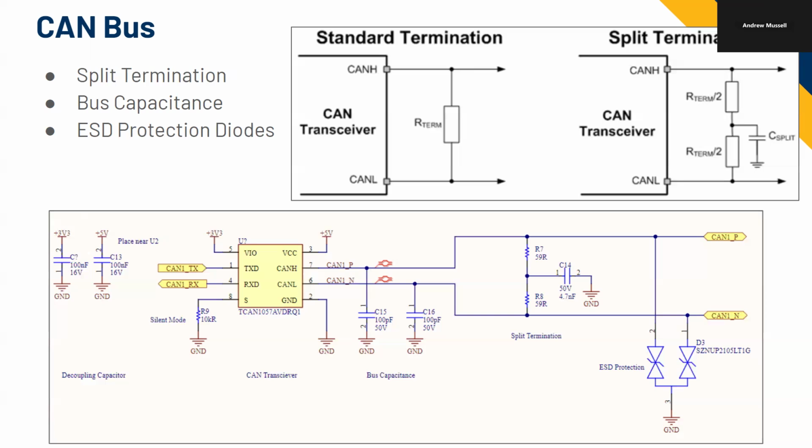We have to have physical fuses as per the rules, but on our low voltage boards, the TPS2482 that we talked about earlier, which uses I2C and does all the power telemetry, is actually an e-fuse chip, which is an electronic fuse. If it senses too much current going through, it has a MOSFET and it'll disconnect power. That reacts much faster than a real physical fuse. Also, real physical fuses burn, so when one burns, you have to go in, desolder it, and replace it.